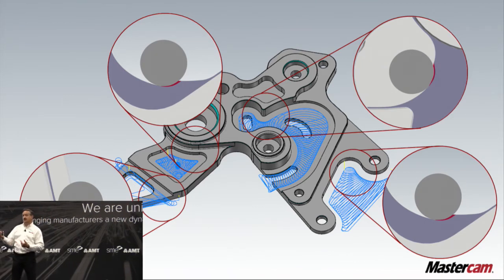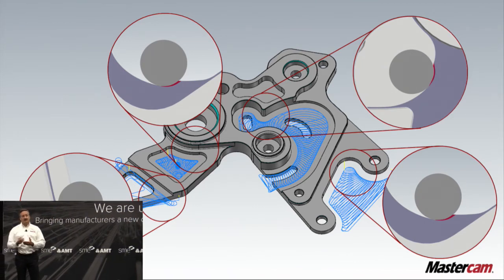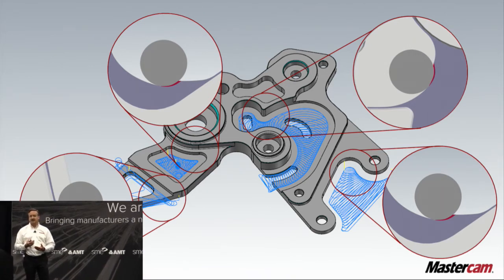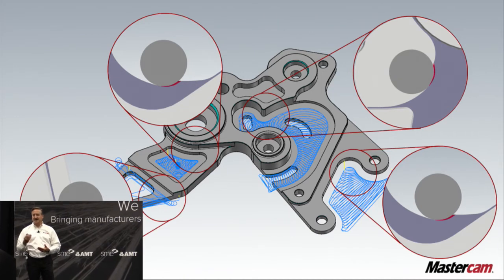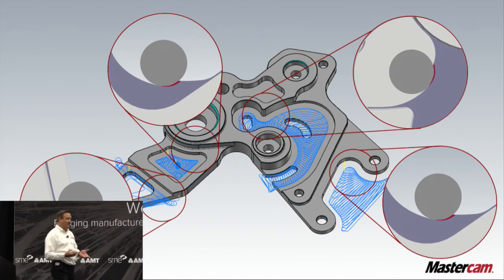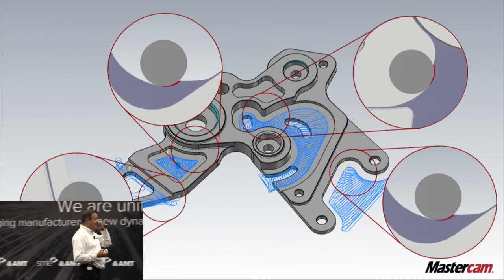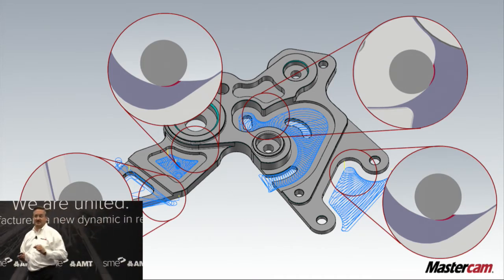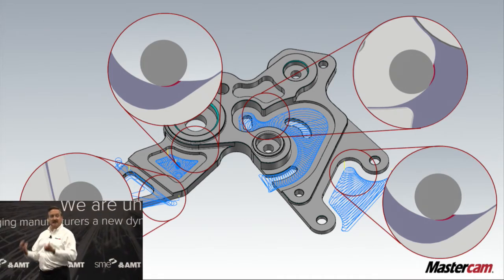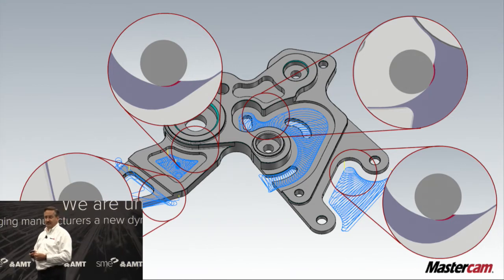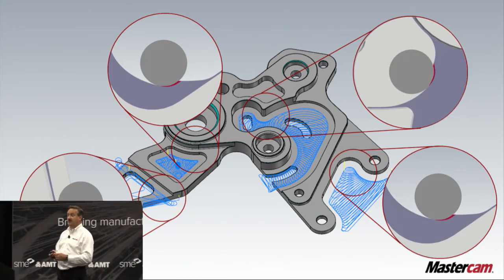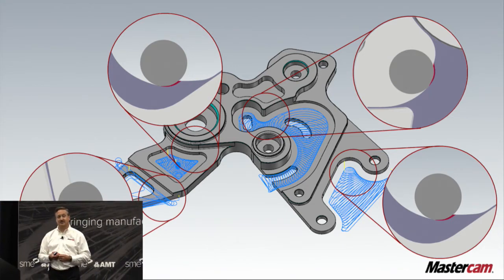By using dynamic motion, ensuring a consistent chip across the entire part, we're putting everybody on a level playing field. However, that points to us saying, I can take that inexpensive tool and bump up the surface speed, and I can also bump up the feed per tooth.